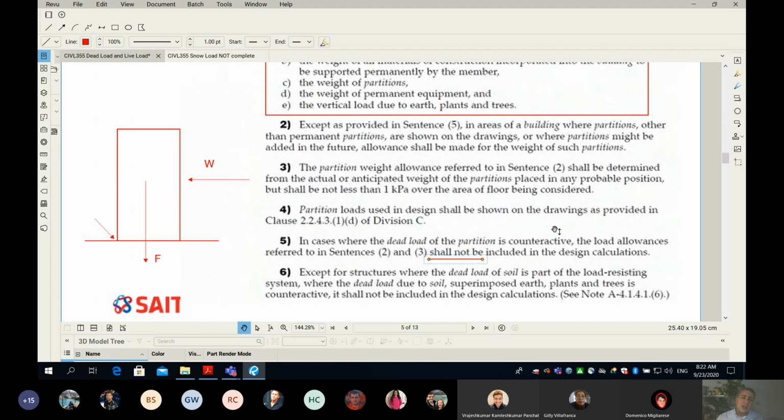So what they do is they will make a plan view, which is just showing the outside, and will leave the partition walls for the future when they have a specific tenant with a specific requirement for their use, then they will build it for them. Okay, so you can see in this case, partition we know is going to happen in the future, but we don't know the exact partition right now. In our design, we should include some allowance for those partitions.